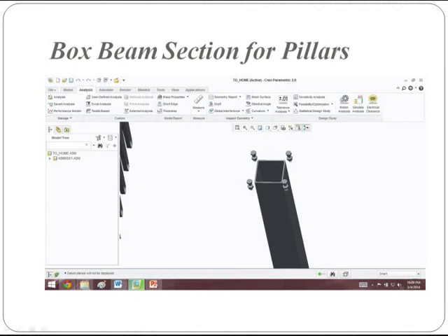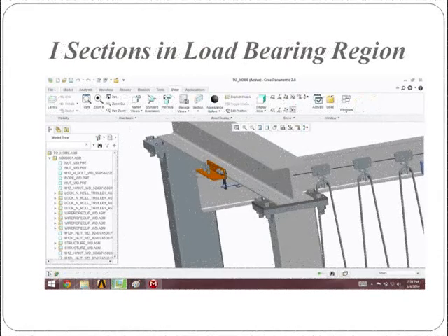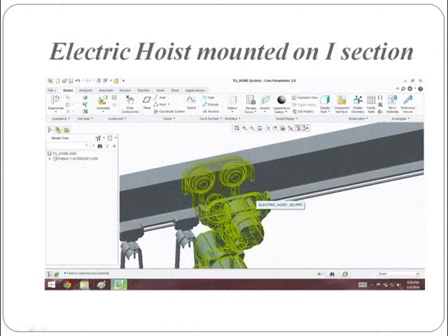Design aspects: it should be easy to dismantle and assemble. It should bear a load of 1,500 kilograms maximum, considering FOS. It should be designed in such a way that it should be portable, i.e., quick to assemble and dismantle. Simplified and powerful design is required such that it can resist the load and the risk of accident and failure should be less. Readily available materials such as common beam sections should be used in designing the portable gantry crane.